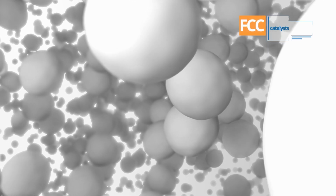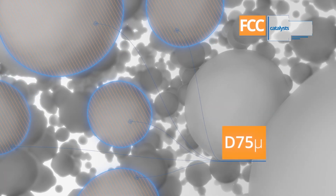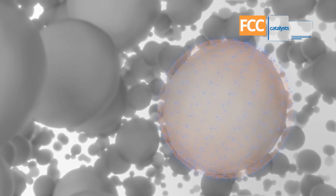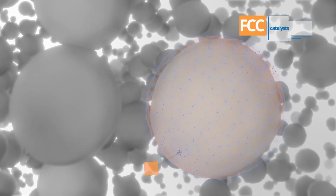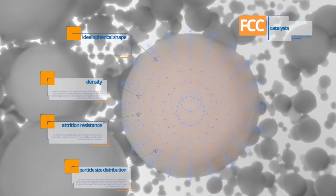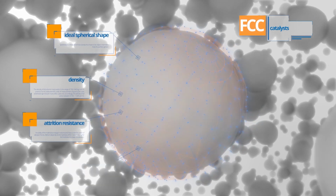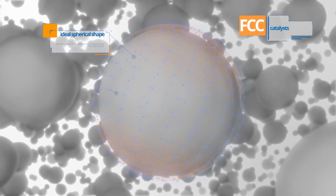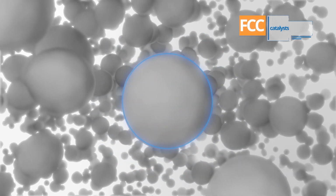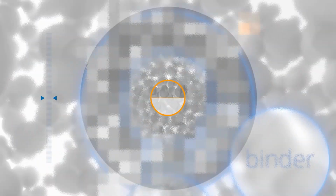FCC catalysts are microsphere particles with an average diameter of around 75 microns. The KNT group manufactures advanced catalysts with exceptional physical properties such as particle size distribution, attrition resistance, density, and an ideal spherical shape. This ensures our catalysts provide excellent catalyst fluidization in the units for stable operation at high throughput with minimum losses. The main components of the fluid catalytic cracking catalysts are zeolite, matrix, and binder.